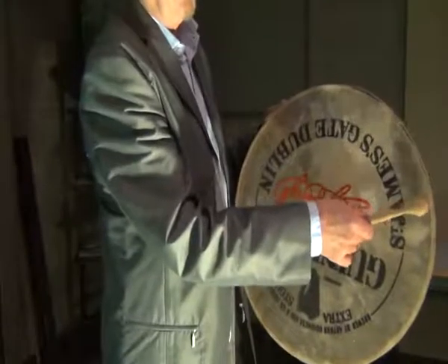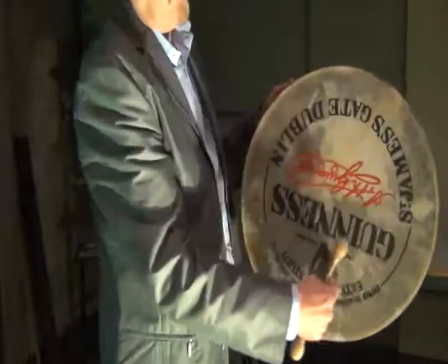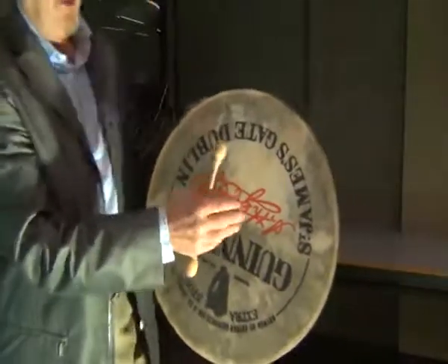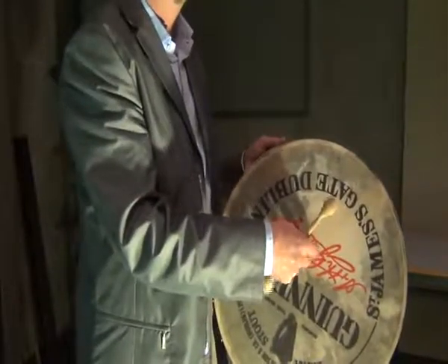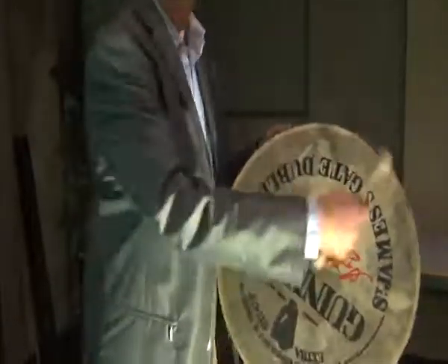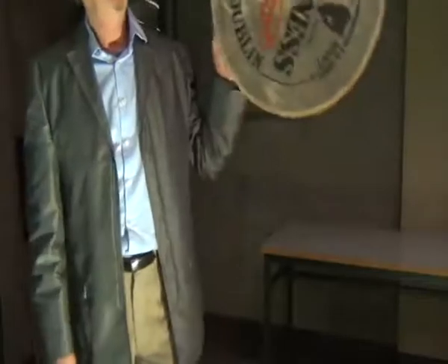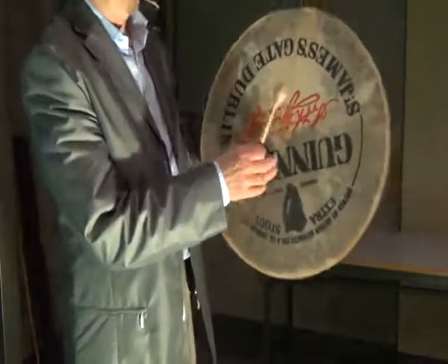Whereas in this case, I'm exciting a ring here. And there's probably no vibration somewhere around here, midway. And then there's a lot of vibration in antiphase at the center. Okay? So we have vibration and vibration in the opposite phase, and nothing in between. So we've got the fundamental mode and a higher mode, which has a higher pitch.